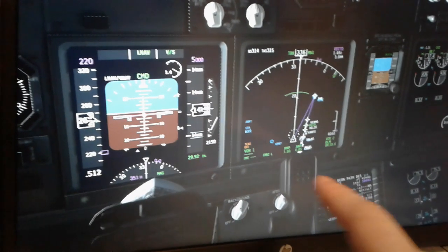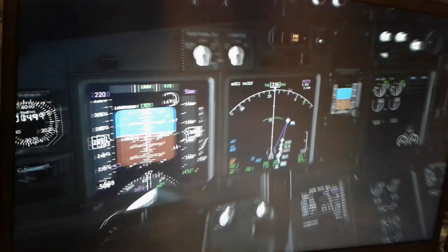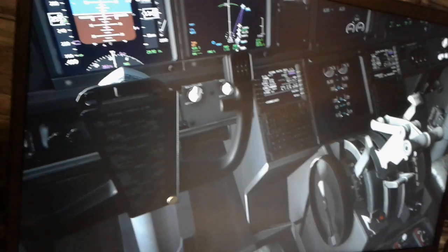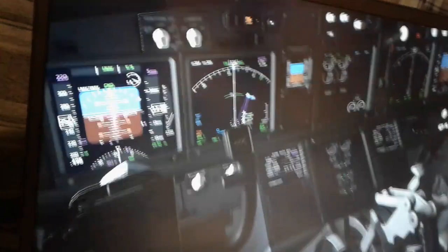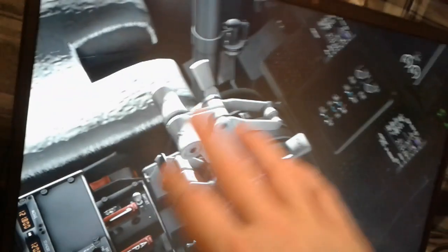So this is the point we need to start turning back for the airport. Use full flaps extended. Now decrease the airspeed even further. A vital thrust position.